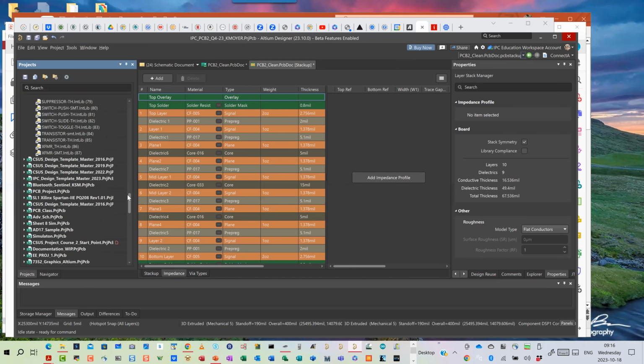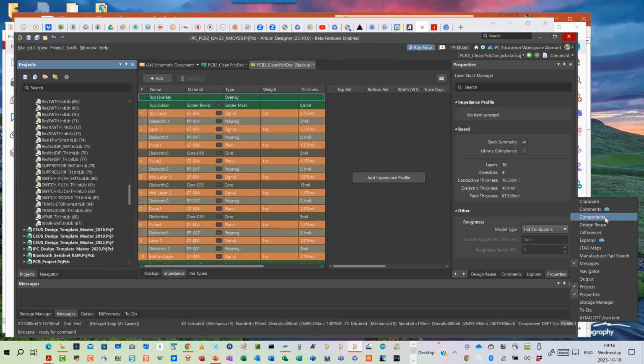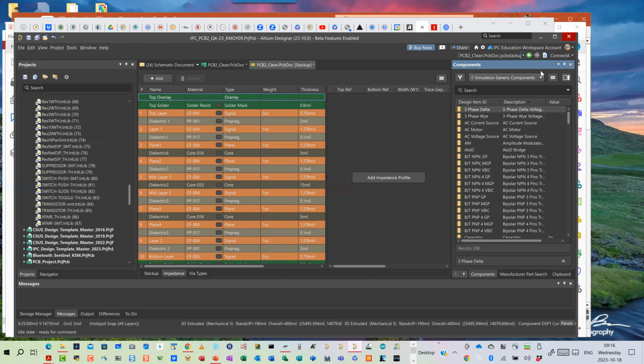So right now you're used to building, for example, individual schematic libraries and individual PCB libraries, yes? Right. You can take those two libraries and create what's called an integrated library, this IntLib, and that IntLib can then go over here. You know how in your components panel you've got all the various predefined Altium libraries, which normally you can't go edit.